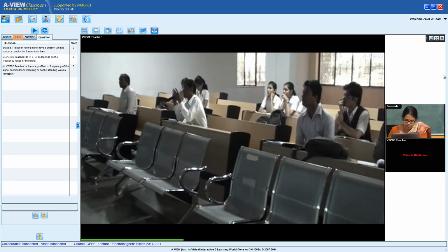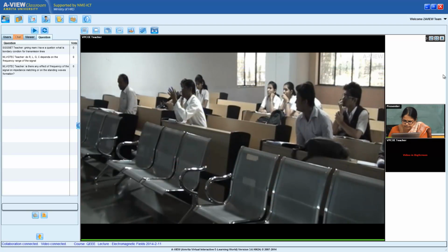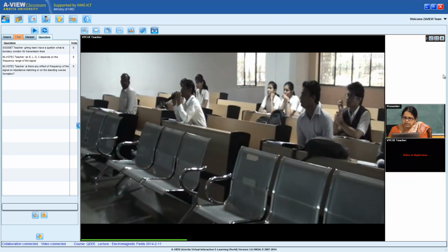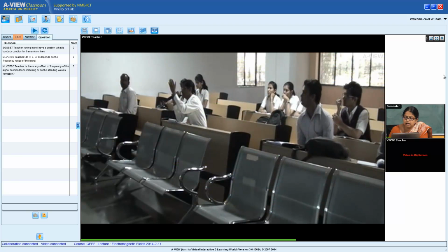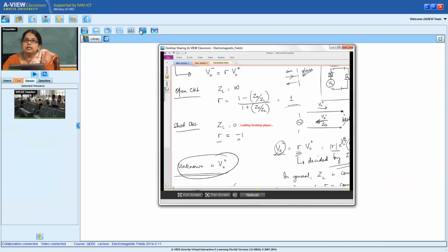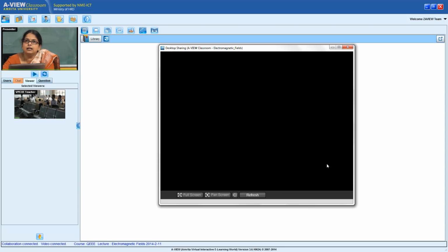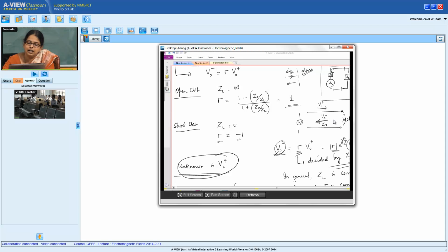But we are taking a glass, some medium is there. For this example, you are taking a glass at the end. I could take any ZL which has an impedance very large compared to air. In fact, the larger the impedance of the medium, the more is my reflection. I get maximum reflection when it is open.